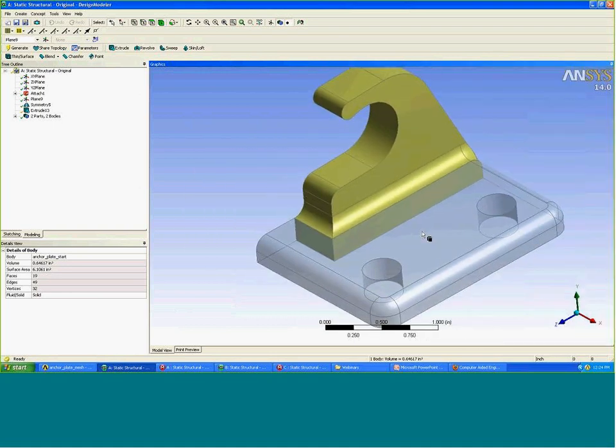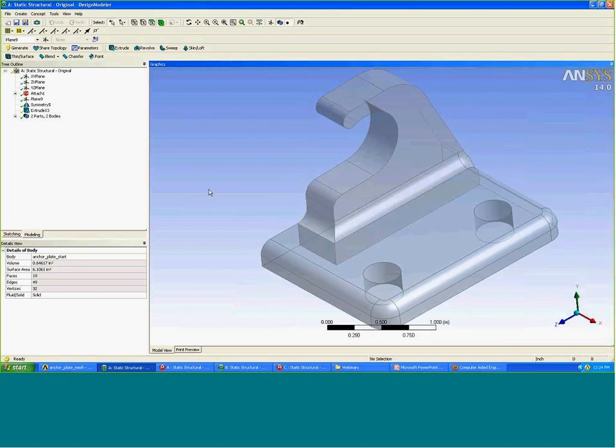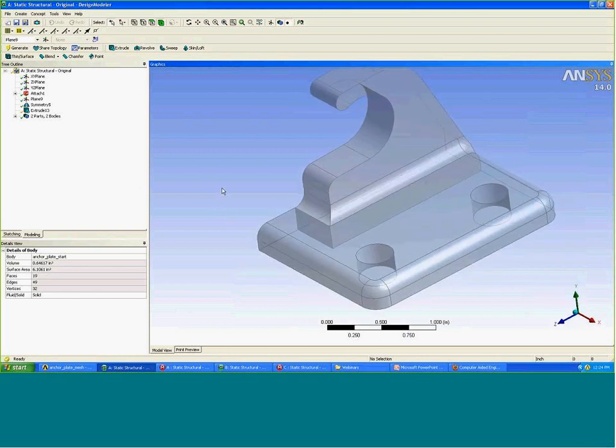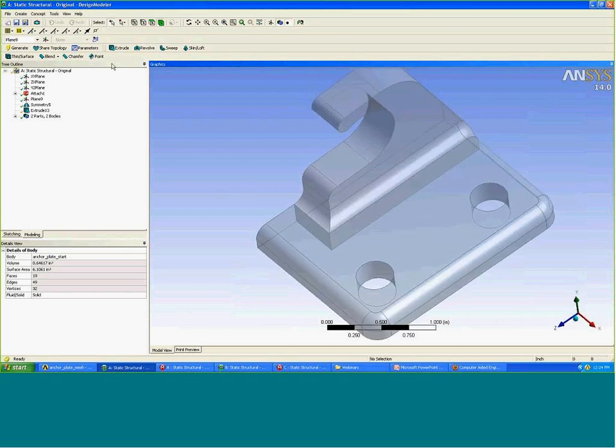So that I generate, you see 2 different parts here. This slice in particular doesn't get me all the way to having sweepable bodies, but it sets me up for my next slice, which will then create 2 additional sweepable bodies. So it's kind of a preliminary slice.